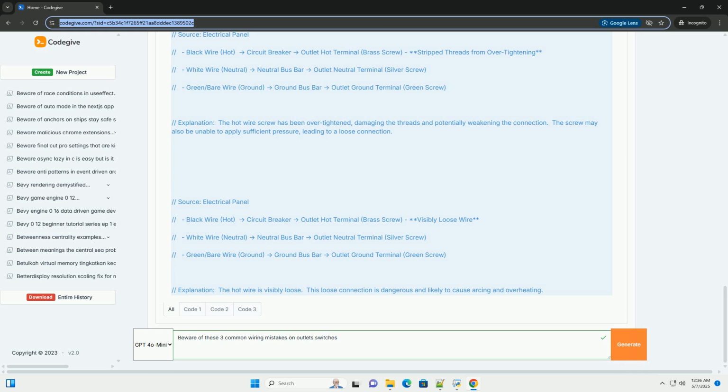Wire connectors, wire nuts: use all listed wire connectors for making secure splices. Electrical tape: for insulating wire connections, use sparingly, wire connectors are preferred. Voltage tester, non-contact: to verify that a circuit is de-energized before working on it. Flashlight or headlamp: adequate lighting is essential for safe and accurate wiring. Safety glasses: protect your eyes from flying debris. Work gloves: protect your hands from cuts and abrasions.